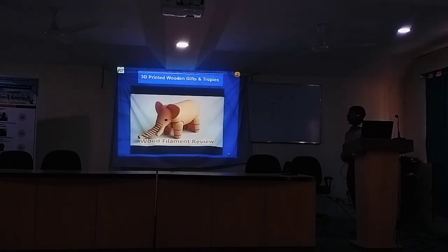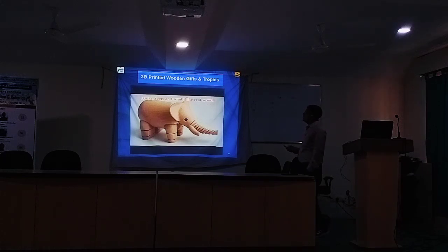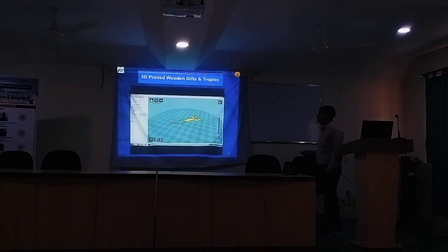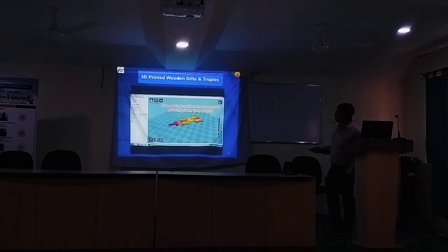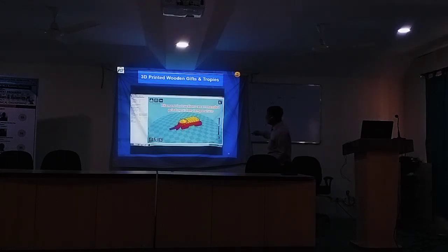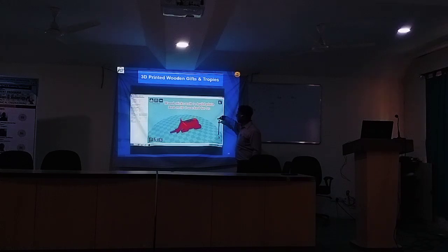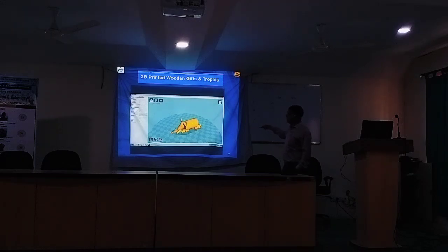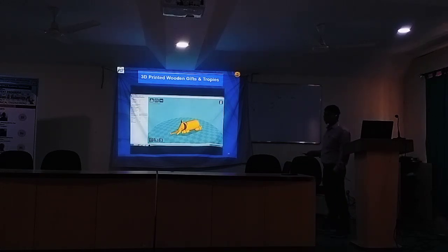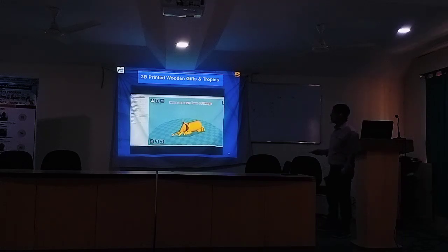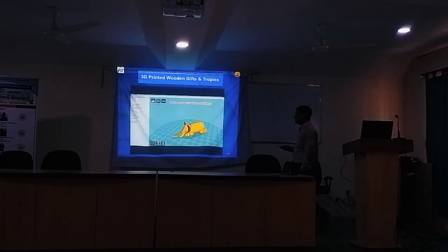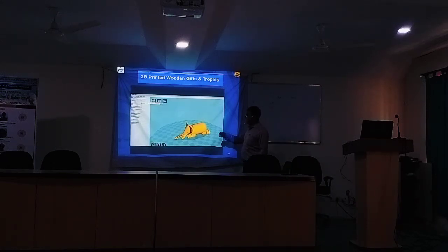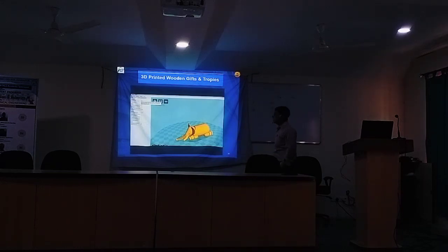3D printing is also used to create the wooden gate or the toffee like here. Here I like to design the inside, so a honeycomb structure or square honeycomb structure is developed. Manufacturing this is very difficult, even impossible, for traditional manufacturing processes. From outside it will be continuous, but inside there is a honeycomb kind of structure. Getting that by a traditional manufacturing process is not possible, but you can easily do it by additive manufacturing because you are developing the material layer by layer.